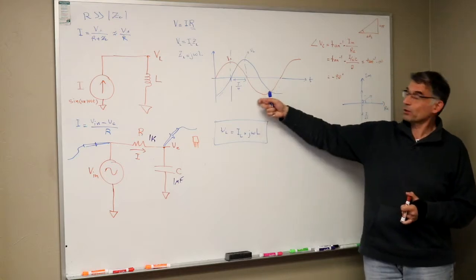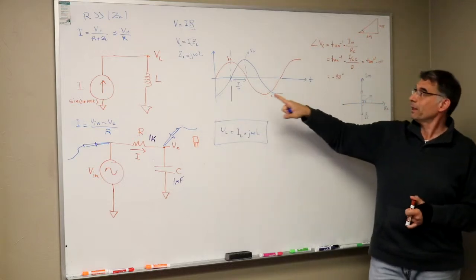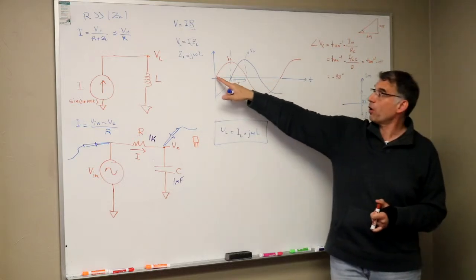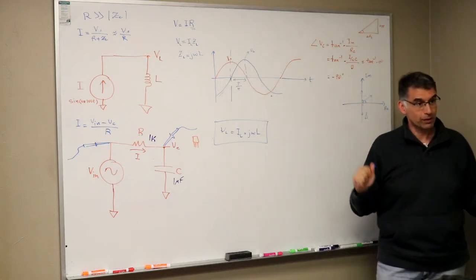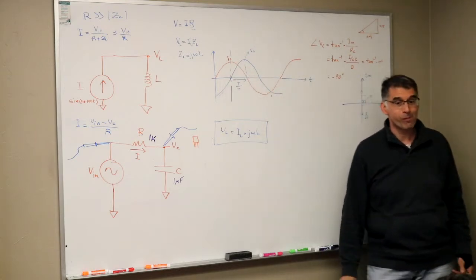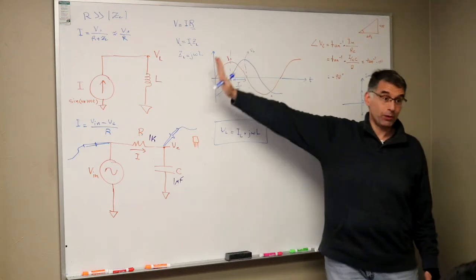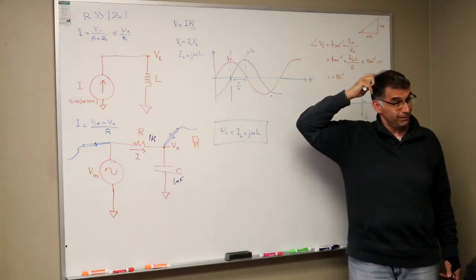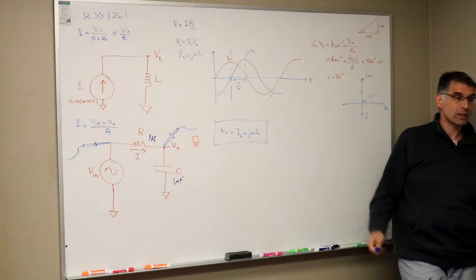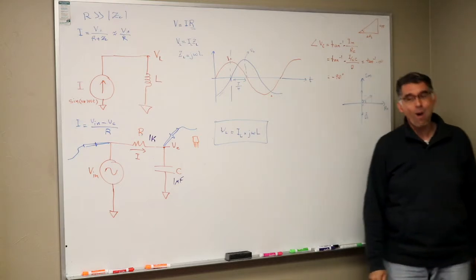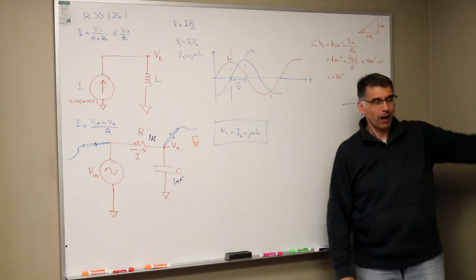So what do you expect to see if we go ahead and simulate that circuit? What do you expect to happen here? If our current looks like this again, it's the same current source. What would we shift it, Austin? Yeah, the current will be in front, or just flip positions. So the voltage is going to be ahead. Does that intuitively make sense? Why would that be? Inductors are physically the opposites of capacitors. Whatever the capacitors do, the inductors do the opposite.